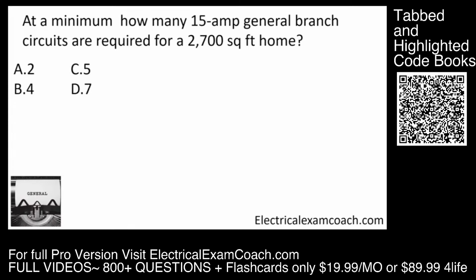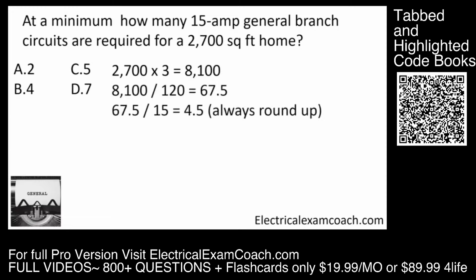At a minimum, how many 15 amp general branch circuits are required for a 2,700 square foot home? The first thing we're going to do is take our 2,700 and multiply it by 3 VAs per square foot, divide it by 120, which is our circuit voltage. Then we take that remainder there and divide it by the size circuit, and in this case, it's 15 amps. It's going to equal 4.5, and we're always going to round up to 5.